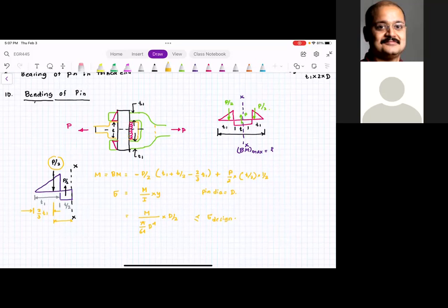However, let me tell you, once the basic dimensions are done, the engineering dimensions are done, what you want to do is construct a CAD model and perform the finite element analysis to make sure that the joint that you have designed can withstand the three-dimensional complex states of stress. Because please understand, even though you are just pulling, because of the geometry, you are going to have shear stresses, you are going to have normal stresses. When these two stresses act together, you are going to have principal stresses. So the analysis that we are doing, we are not doing principal stress analysis, not even in 3 dimensions. We can't do that by hand.